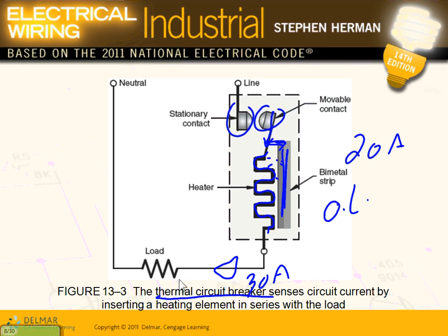Will they come back? Yeah, oh yeah, they will cool down, and after it cools down, it closes. But it takes time. If you go to a circuit breaker, guys, and it keeps tripping, if you try to reset the circuit breaker, it won't reset. It needs some time, a couple of minutes, maybe 10, 20 minutes to cool down so it can close. Like an overload, it's very similar.